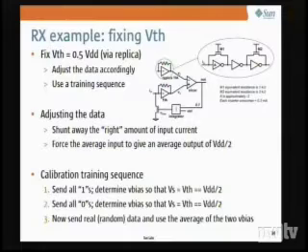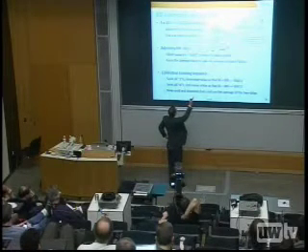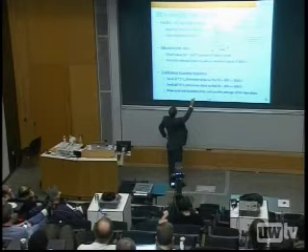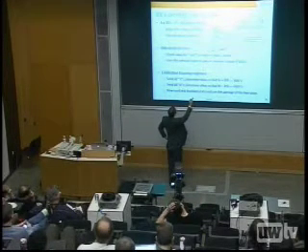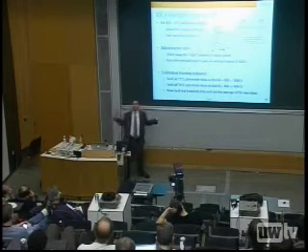And so what we did, and I wish I was much taller to actually point at this, but we had the input coming in from the left, I in. Maybe I can, you guys gave me a pointer, I might as well use it. So the input comes in here. Right? It's going to feed into a transimpedance amplifier, and that gives me a signal here. Well, I'm going to compare that with a threshold voltage, which I have fixed to be half VDD. Right? I've declared my threshold as half VDD.